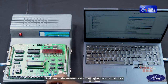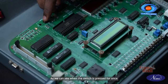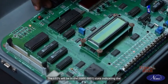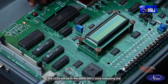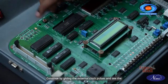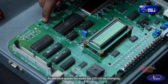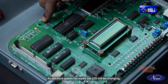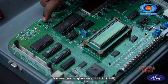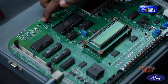Navigate to the external switch and give the external clock pulses by pressing the switch. As we can see, when the switch is pressed once, the LEDs will be in 00000001 state, indicating the count of the clock pulses. Continue giving the external clock pulses and see the change in the LED state. As the clock pulses increase, the LEDs will keep changing. The maximum we can give is only up to 11111111, FF.